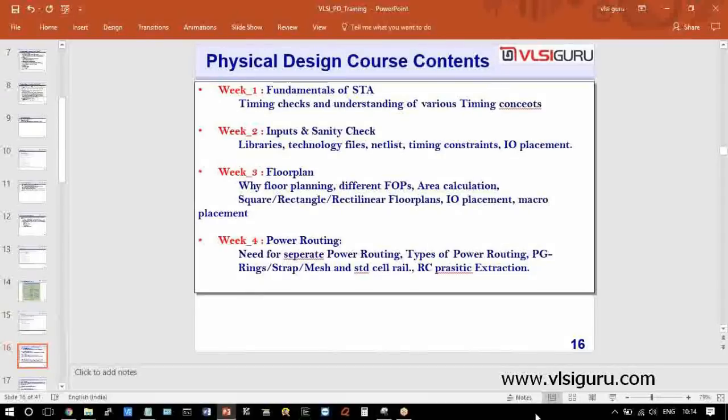It is because by the time it comes to open the gate for you, the current density reduces. If it reduces, the gate opens slowly. If the gate opens slowly, that cell will work slowly. If the cell works slowly, will you be able to meet your frequency? What are we dying for? We are all dying to meet timing at the end of the day. We will not be able to.